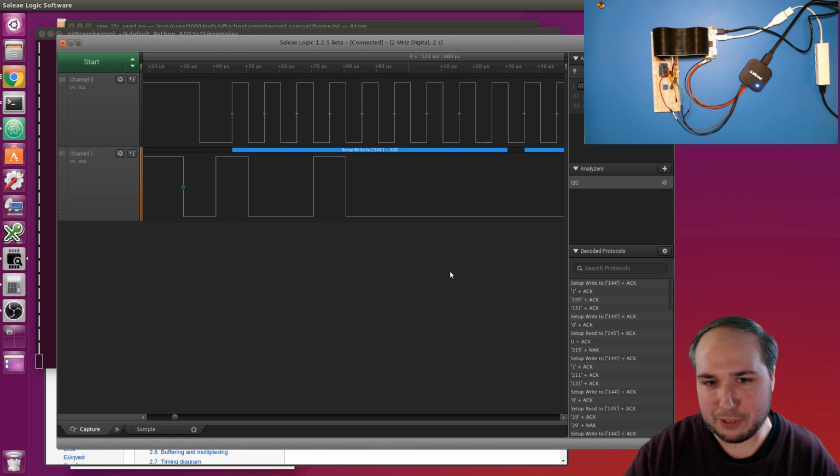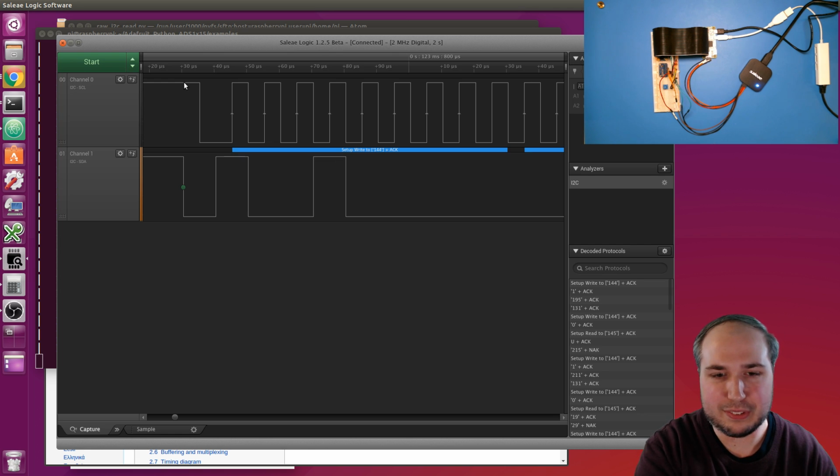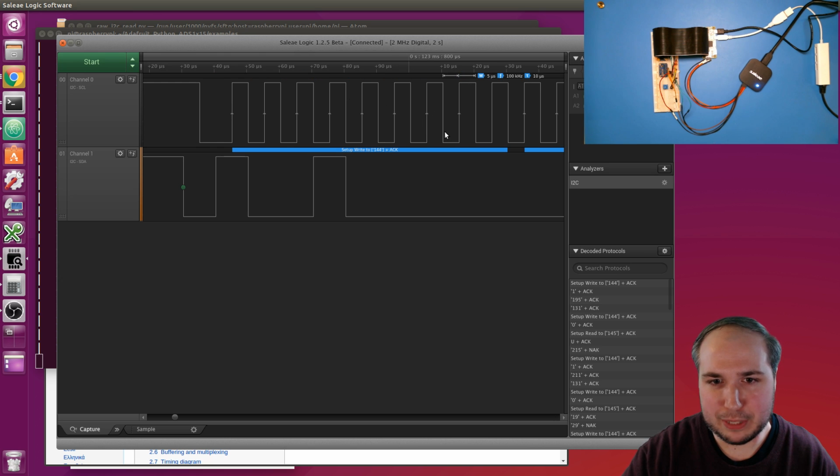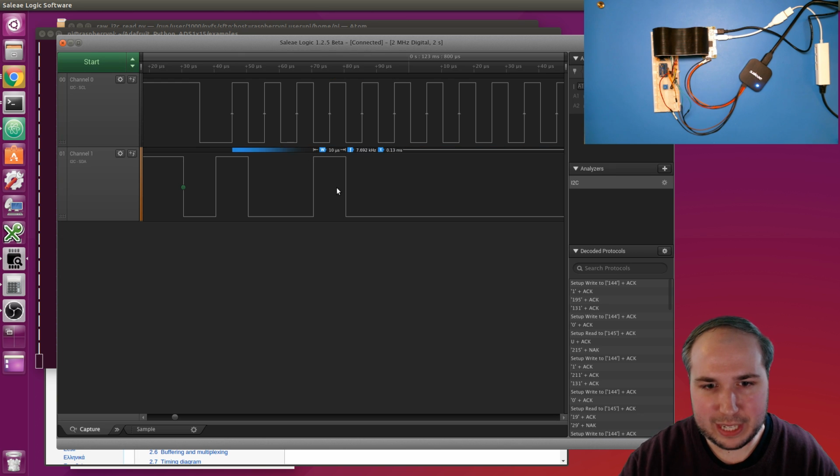That ninth bit is the acknowledgement. What's happening at the very start is the code running on the Raspberry Pi says, okay, I want to talk to the ADS analog to digital converter. In the data sheet for that device, you can look up what the address is. The address is a hex value of 48, so it needs to send that hex value of the address out to the I2C bus. It clocks out all of the bits, at least 8 bits of that address, and the data line goes high and low to indicate that value.